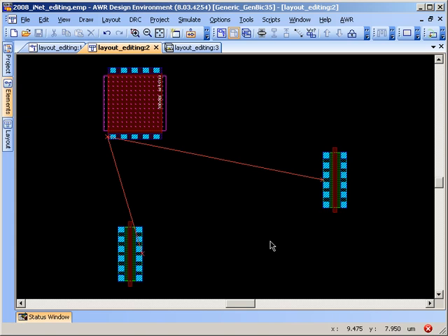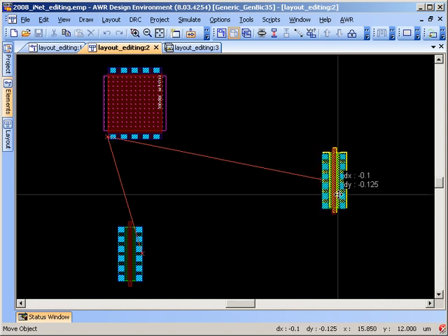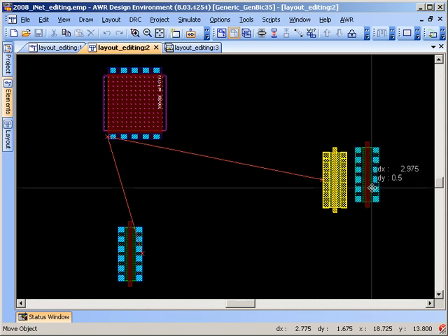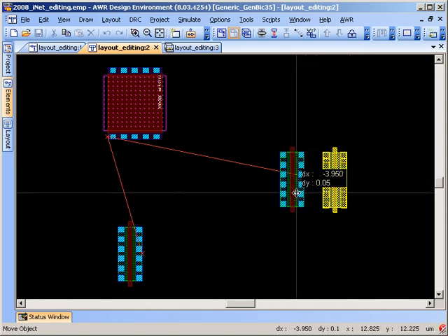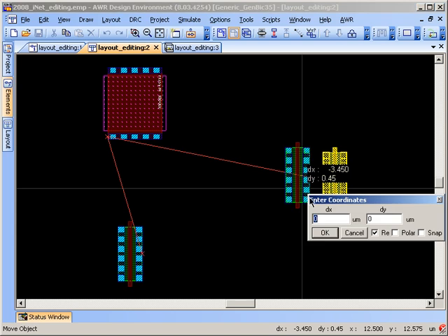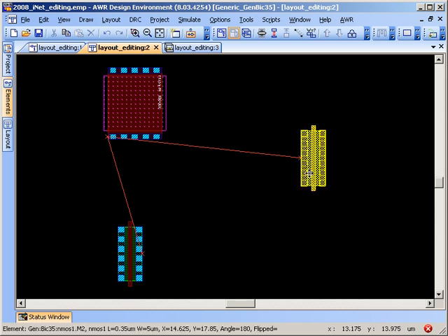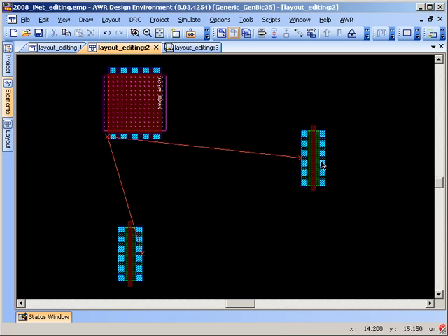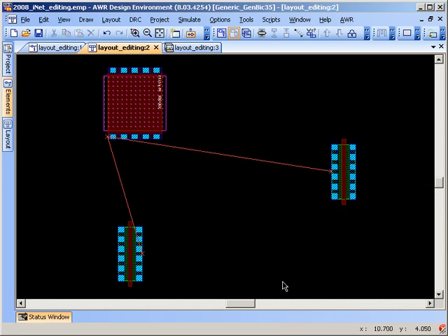The first thing is an improvement to the coordinate entry dialog when routing. We have a coordinate entry dialog that you can use anytime you're doing any layout operation. If I start to move this NMOS device around, I can hit the tab key and say I want to move -2 microns, so moving to the left, and 2 microns up, and that'll move me by dxdy. Or when I hit tab, I can also uncheck the relative box and enter an exact coordinate, and that works when moving or stretching or creating rectangles or polygons or any operation.